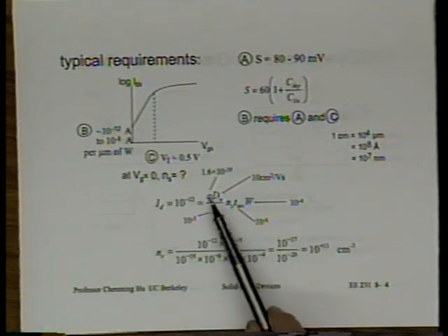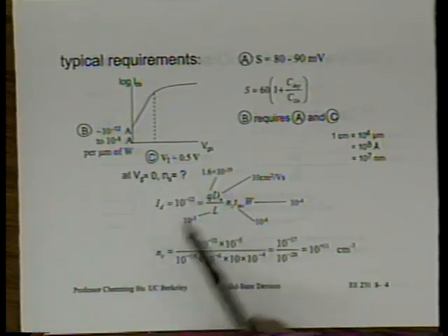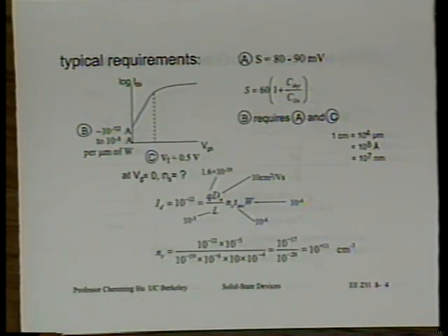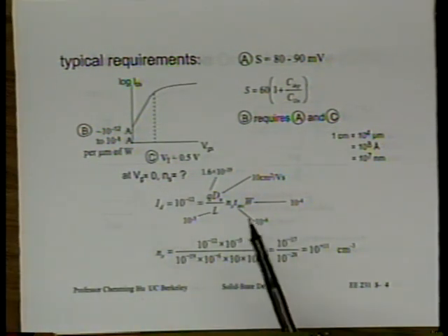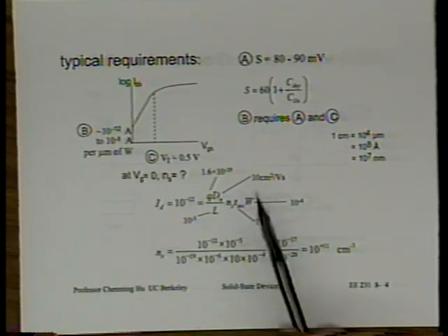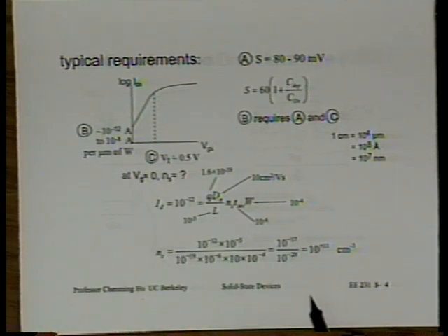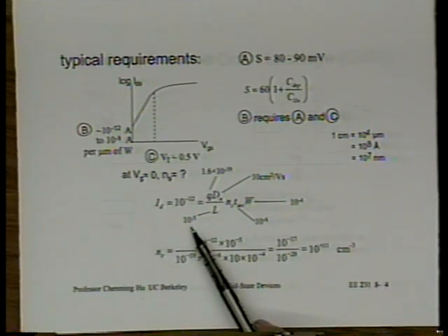Well, what we know, Q is 1.6 times 10 to the minus 19. Do you remember what's the typical number for the diffusion constant? Just order of magnitude. If you tell me 10, that's a very good answer. If you say 30, it's okay. 5, 3, that's okay. 10 centimeters squared per second. Channel length, let's use 0.1 micron, which will be 10 to the minus 5 centimeters.